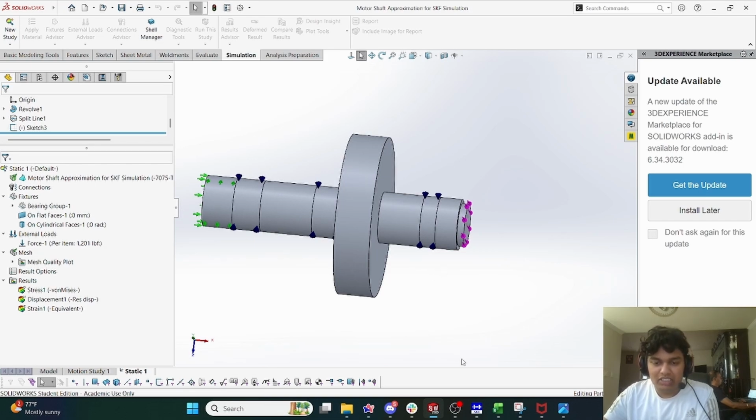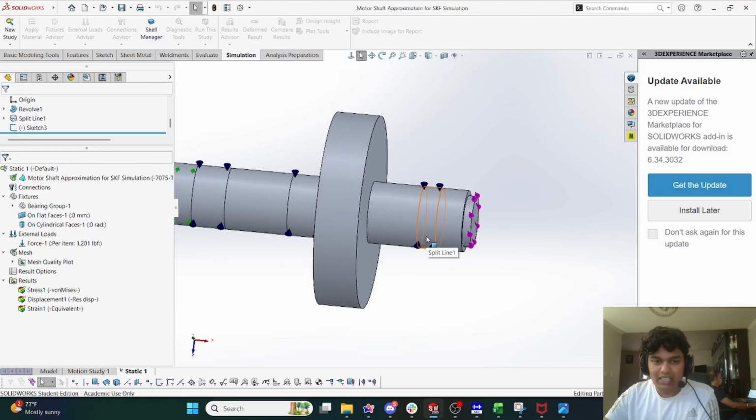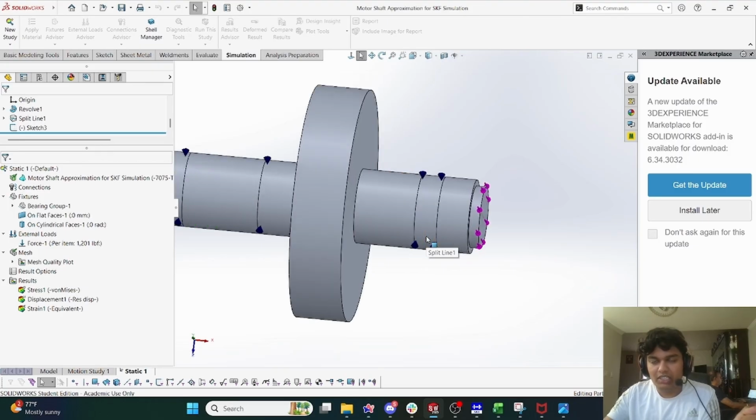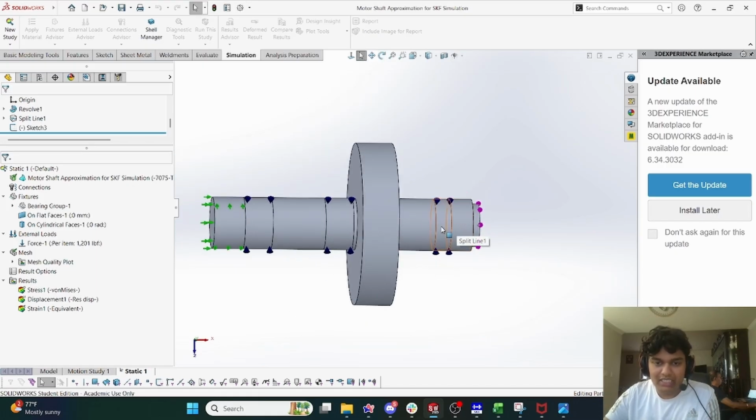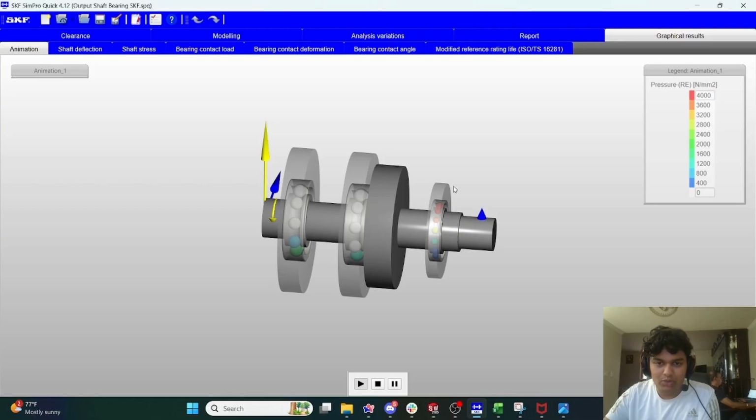And so that means I can trust SKF's answer, because the stiffness I put in that got me 6 kilonewtons was clearly less than the actual stiffness of the bearings. And the load that SKF is telling me is less than for fully rigid bearings, which matches intuition and reality. So we can trust SKF's numbers. So now we have the actual load of 7.234 kilonewtons.